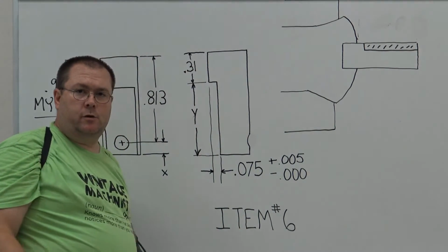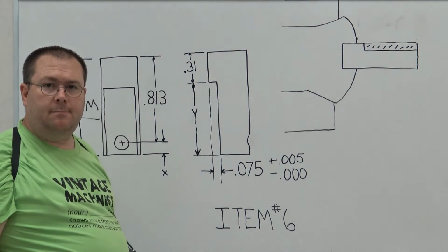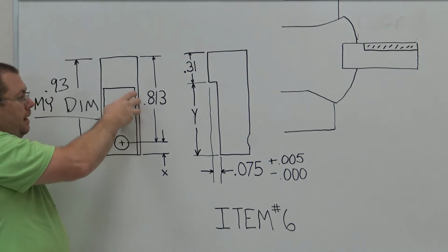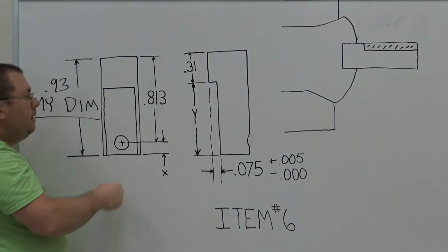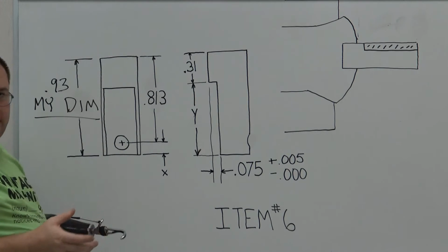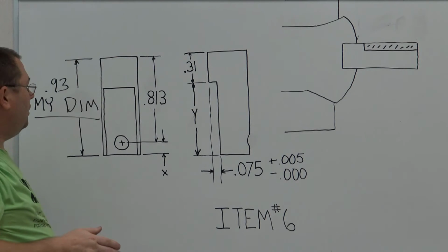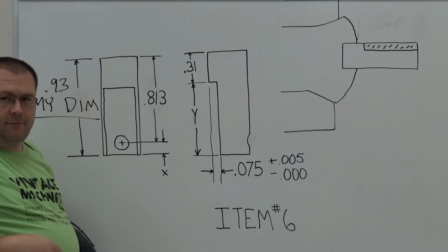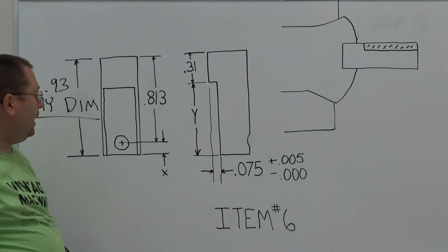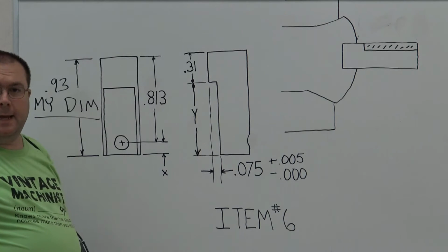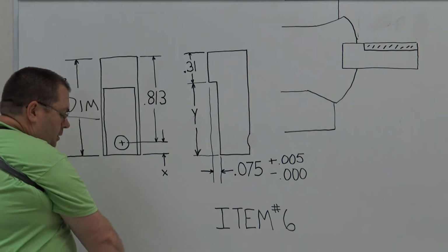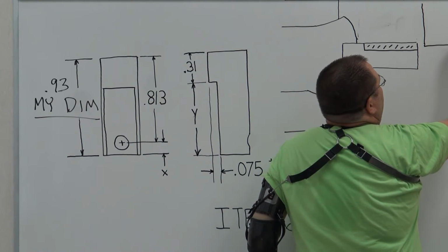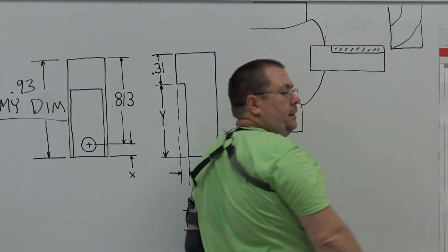What kind of a tool are we going to use to machine that flat on? We're going to use an end mill. I would like the end mill to be wide enough that it will cut the entire width of that flat at one time. Now this piston is 1/4 of an inch in diameter. A 1/4 inch end mill will do the job, but it's definitely more work for you. So you have a 5/16, a 3/8, and a 1/2 inch in your toolbox. I'm going to prefer to use the 3/8. It's just what I've always used. Okay? So your 3/8 end mill is going to be sitting up here like this, right? And your flutes come up around like so.